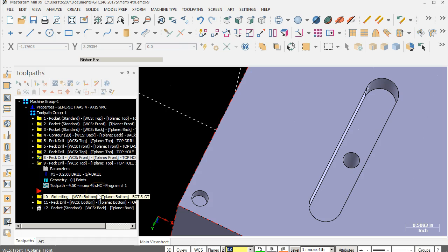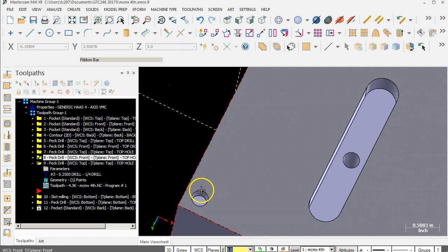And then, worst case is we're going to be running in Verify, and Verify pixels are cheap. And we're going to see this whole side blown out because the tool holder went through and took out a lot of extra material. So another advantage of checking clearances, we're looking for those collisions. Having the tool holders in this case is pretty much a must.